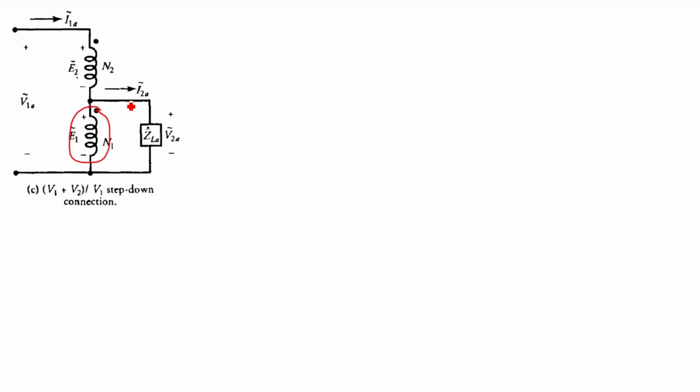So therefore now I can draw here the core loss resistance and your magnetizing reactance. So core loss resistance will be here RC1 and it is XM1. Similarly other resistances and reactances can be drawn in the respective windings.